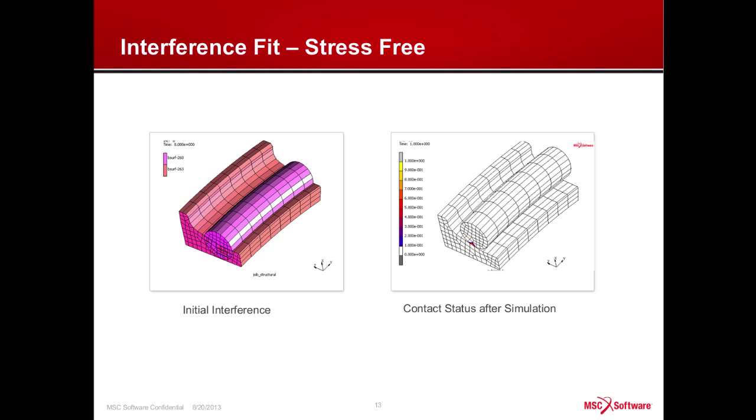We do have this penetration here, and in this case, we just want to move it up, but we don't want any stress buildup here. So we have this simpler model just to demonstrate this particular capability. You see that the interference is removed and there's no specific stress. It is detecting contact in this region, so you can see by the color change where there is some contact.